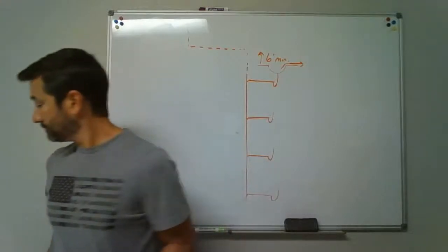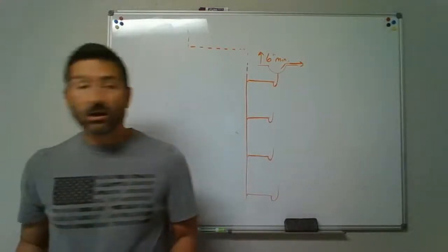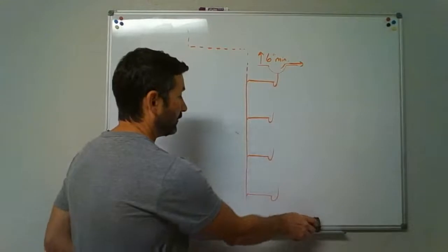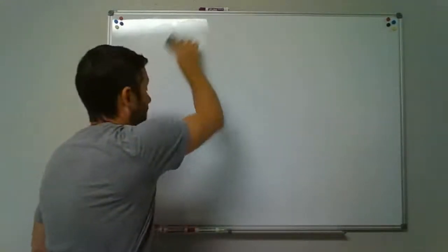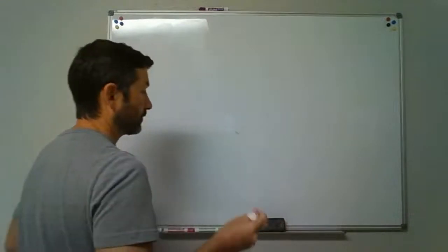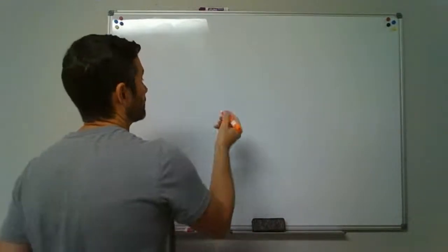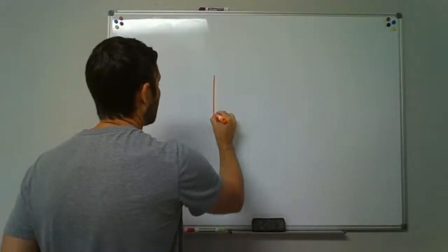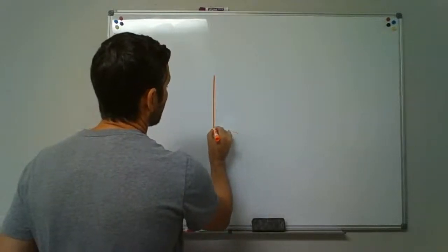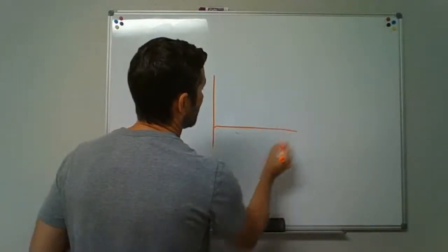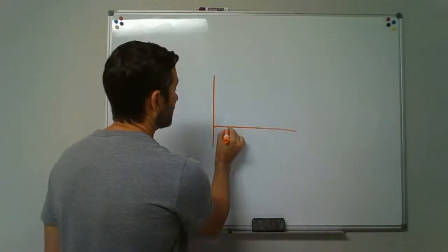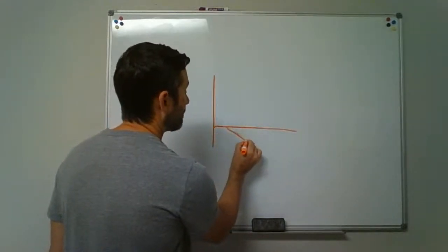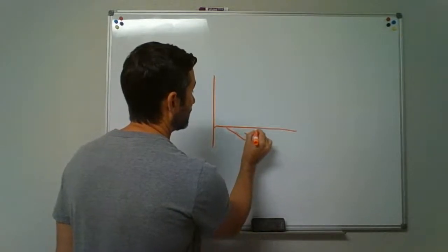Circuit venting. You're not going to see that in residential. It's a commercial venting method. But let's just say we have a stack here. We'll take a horizontal branch or branch interval coming off of that stack. Now, if we circuit vent, what it's allowing us to do is take a battery of fixtures.